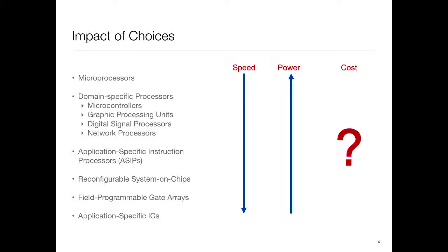Let's look at cost numbers, right? Microprocessors, server class processors are probably a few $1,000s. More typical desktop type processors are a few $100s, and microcontroller type, DSP type of stuff are, let's say, on the order of $10. Okay, FPGAs, stuff out here. High-end FPGAs could be $20,000. I mean those big Xilinx FPGAs can be pretty expensive. More modest FPGAs would probably be, say, on the order of $100 or so. And there are of course really low-end stuff also.